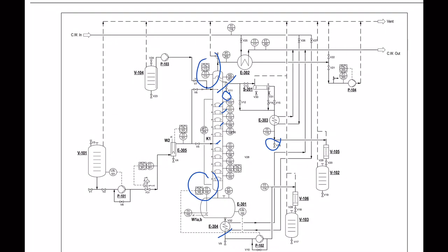Okay, then you have to set the reflux divider back to the original setting. Just now from position 1, now you turn to position 0, which is total reflux. That is the first option to collect the top product sample.